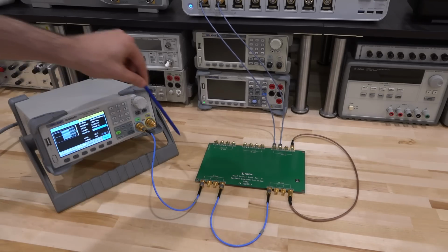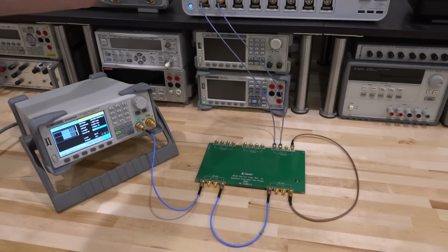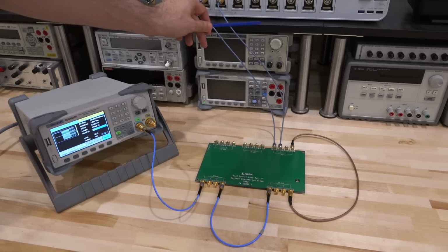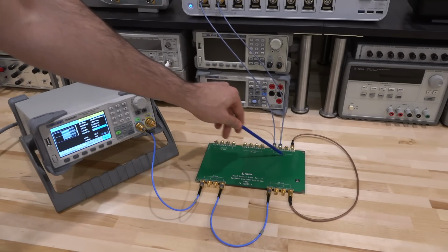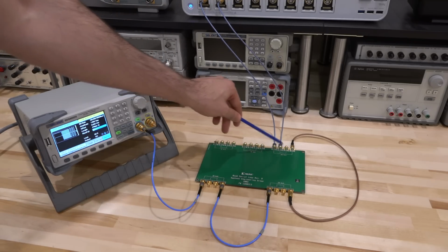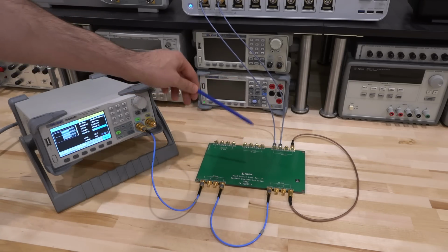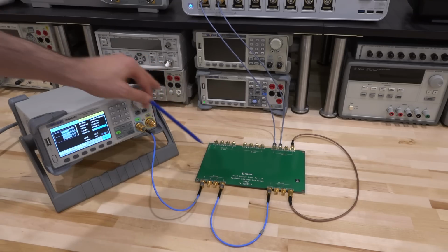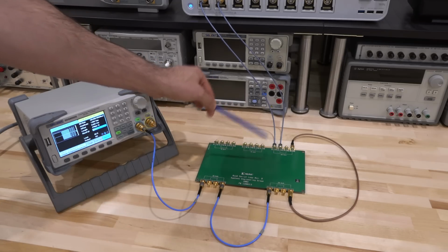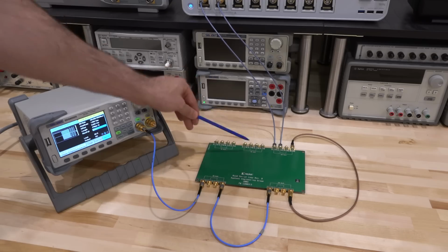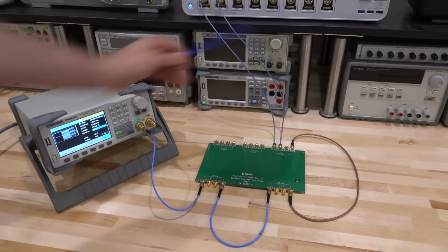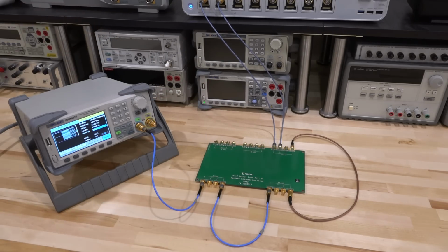So the signal goes through all of the traces, goes to channel 1, and on channel 2 of the scope, up here I have the signal on the 40-inch trace on the differential line, the crosstalk between two adjacent lines being monitored. So I can not only look at the signal after it's gone through 90 inches of trace, but I can also look at how it behaves once it's coupled to an adjacent line, and see the influence of the coupling also on the oscilloscope. So we can see crosstalk and ISI at the same time, which is quite nice.